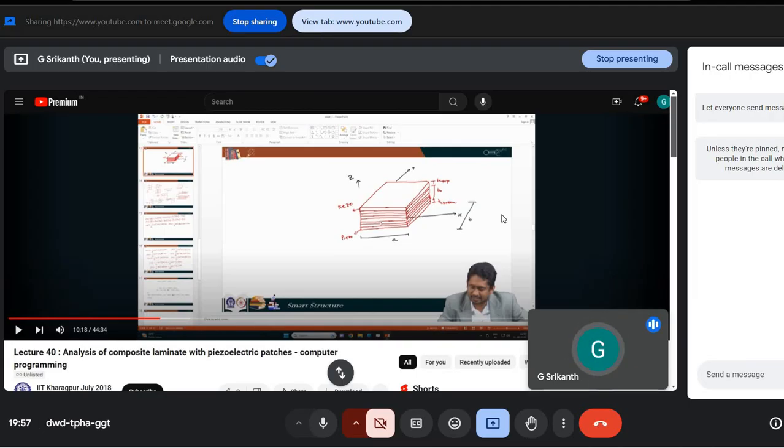When you open the valve, the change in temperature divided by the change in pressure is always constant. This constant was called the Joule-Thomson coefficient. If the Joule-Thomson coefficient is positive, then the gas expands and the temperature drops. But there are some gases that have a negative Joule-Thomson coefficient at room temperature. The Joule-Thomson coefficient is temperature dependent. Past 600 Kelvin, even nitrogen will heat up when it expands through a valve.